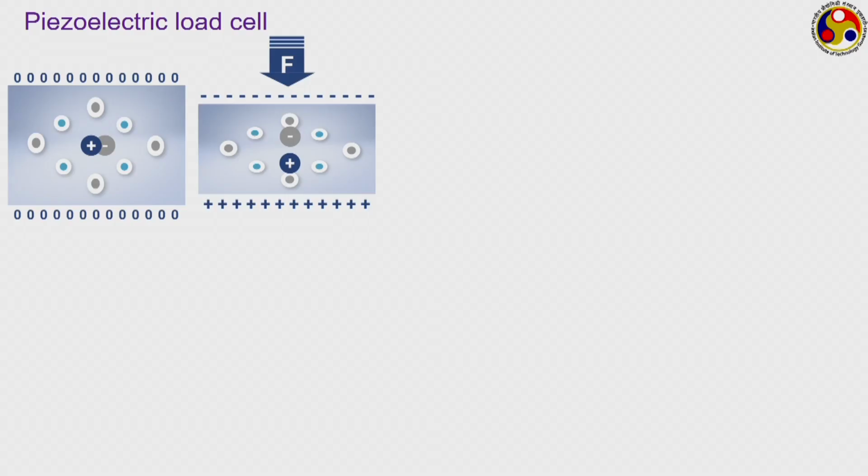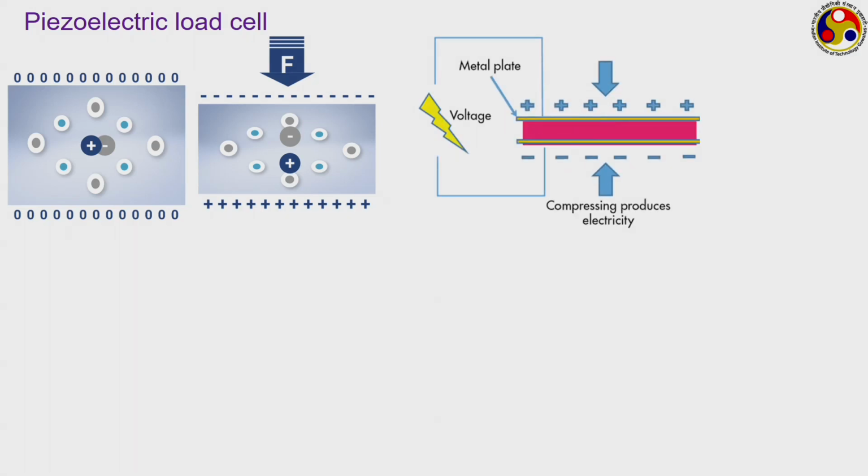Without going into too much detail, what happens is that initially the positive and negative ions are uniformly distributed over the entire crystal body, but when they are subjected to a certain kind of stress, compressive or tensile, some kind of force or pressure, then they distribute themselves such that one side develops a net negative potential, the other side develops a net positive potential, and thereby it is possible to get some kind of flow of charge if we connect them by an external circuit like this.